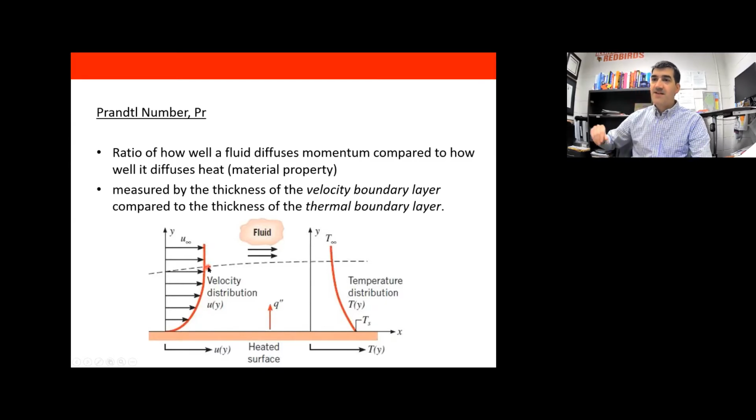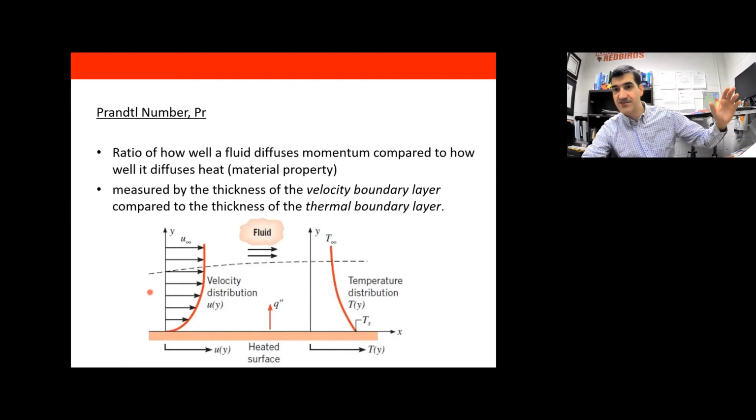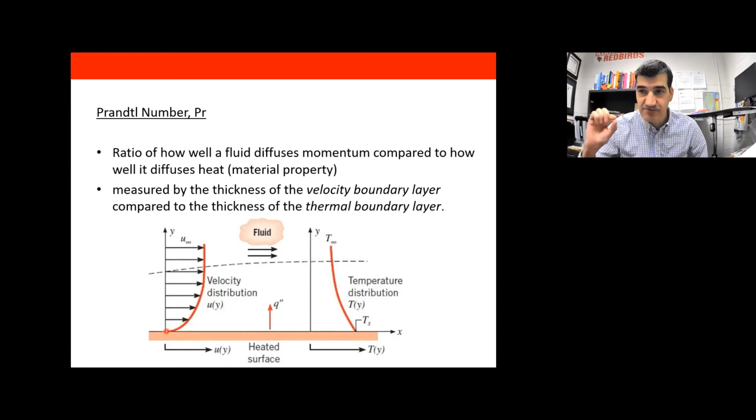All right, so when you've got a fluid flowing over a solid surface, you've got friction at the surface. So this is all fluid right here, and it's traveling left to right across this solid surface. At the solid surface itself, there's something called the no-slip boundary condition, which is universal in the field of fluid mechanics. Right at the solid surface, that friction makes it so that the particles of the fluid do not move relative to the solid surface.